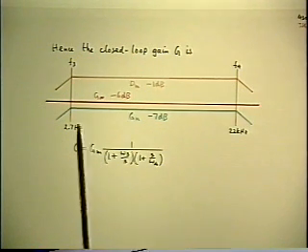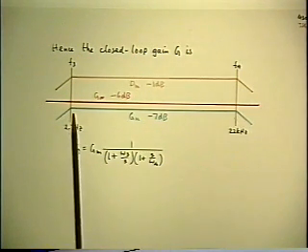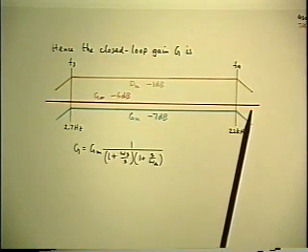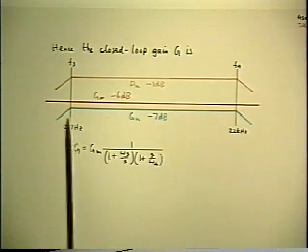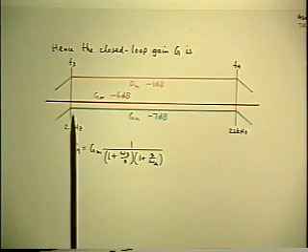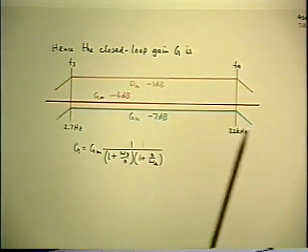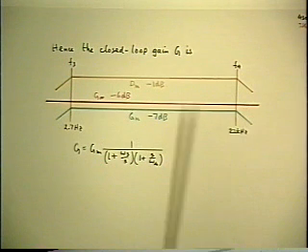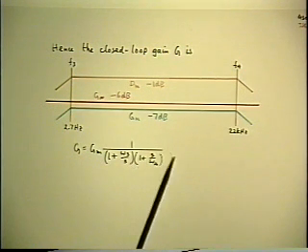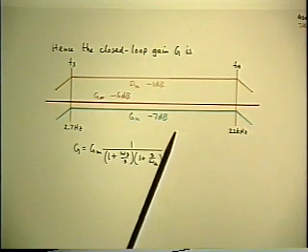So the conclusion is the actual amplifier will give you a gain which is pretty close to the ideal value, the specification, over the frequency range, 2.7 hertz to 22 kilohertz, and beyond those limits, the actual gain will drop off, will deviate significantly from the G infinity. I've purposely chosen numbers that make this rather a poor amplifier, just so you can illustrate the relationships.